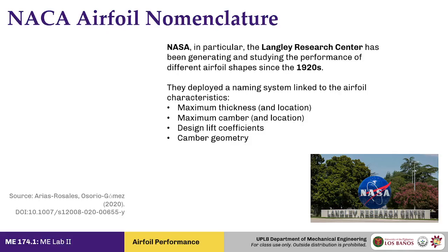So NACA or NASA then had this particular research center, and they've been doing a lot of these airfoil tests for 100 years now. They had this particular naming scheme that is quite convenient because the naming scheme they chose actually displays key characteristics of the airfoil from outright.